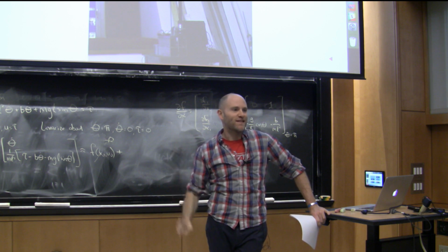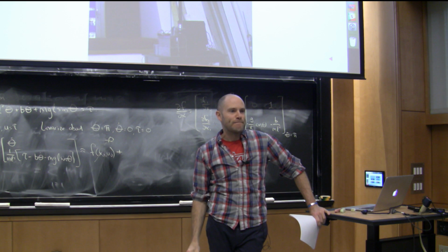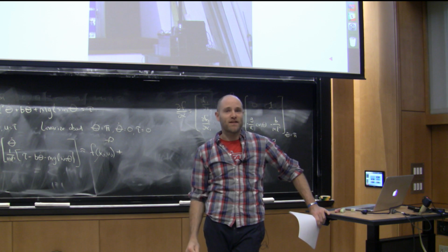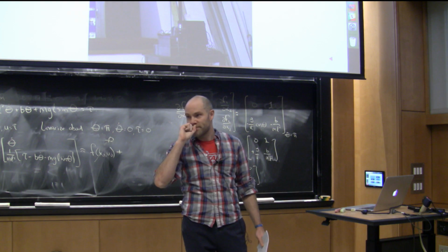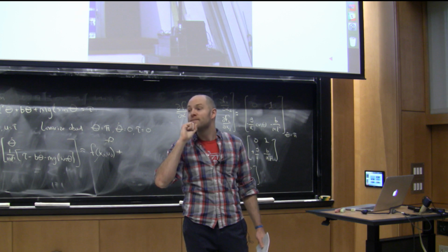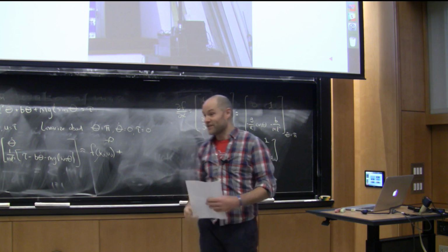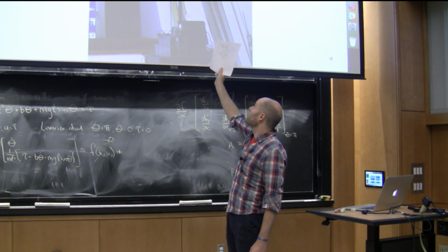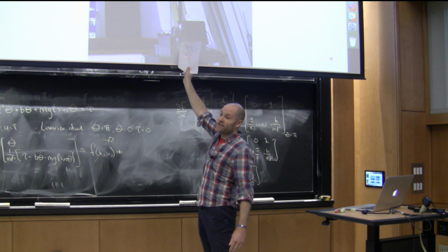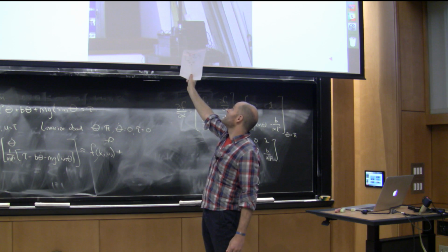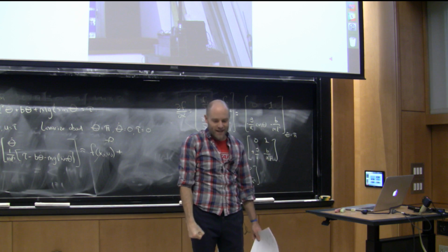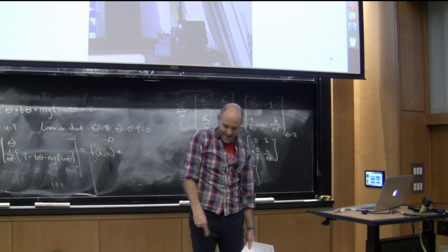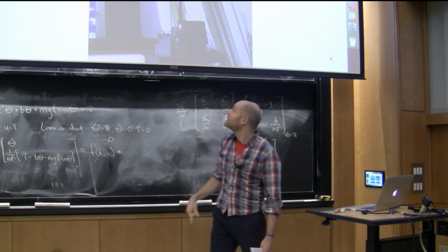Why would I want a slug on the end of that? Slow it down a little bit. It's not quite. We're going to see it. It's going to pop out of the equations exactly next time, but you can guess it now, maybe. I mean, the energy your Acrobot can acquire by moving it ahead is really not inertia. Yes, that is the right intuition. Basically, the control authority that you have on this joint at the shoulder depends on the inertial relationship between the first link and the second link. If you have a big, heavy first link and an itty bitty second link, then you're going to go like this all day long and nothing's going to happen, right?